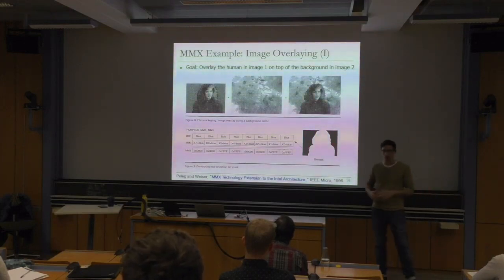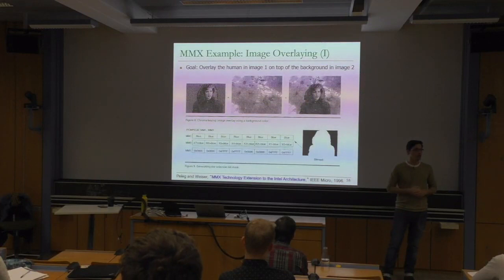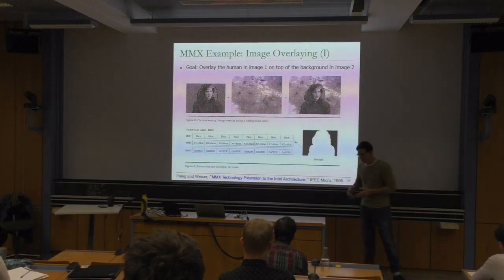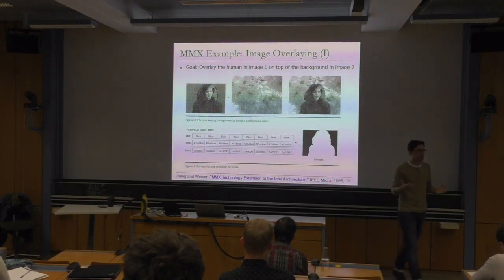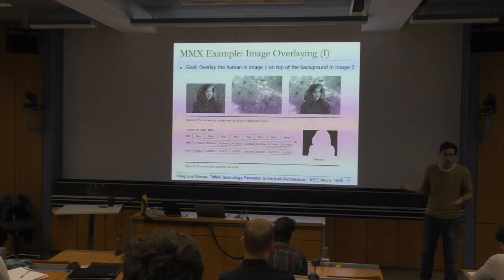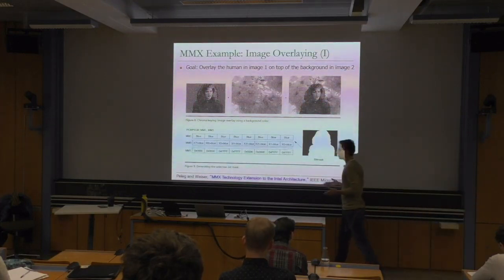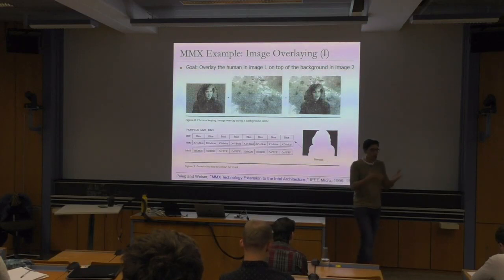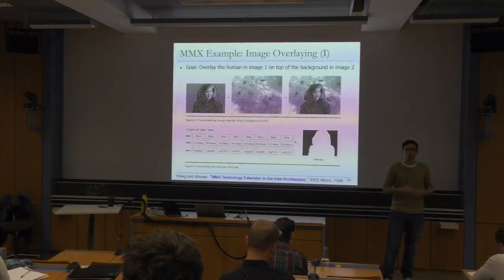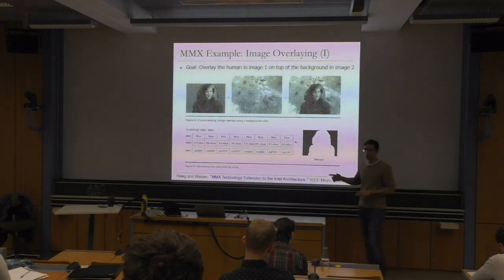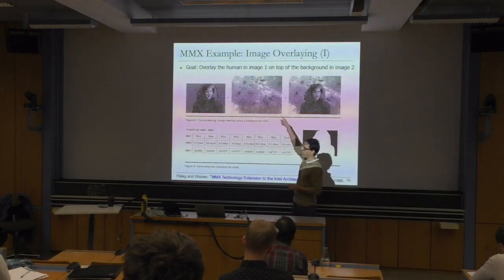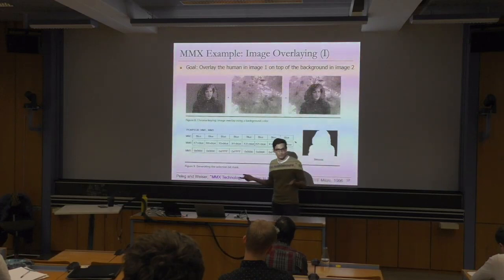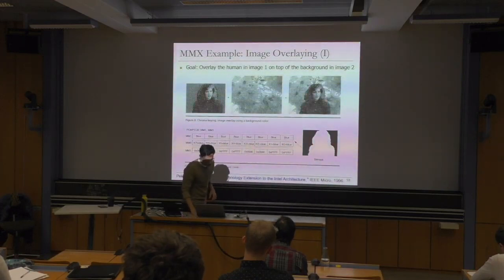Same as these days we have, for example, many AI applications, and we start to incorporate all these applications in our computing systems. In the 90s, something similar happened to multimedia applications, and that's why Intel engineers thought, okay, it might be a good idea to incorporate in our ISA specific instructions that can operate on multimedia data, right? And that's what MMX essentially means: multimedia execution. So that's where the acronym is coming from.